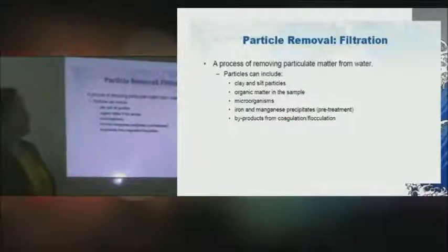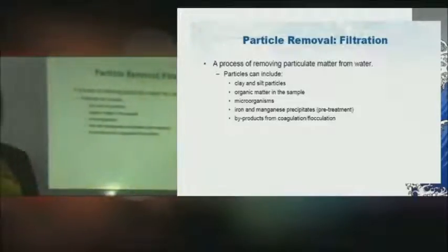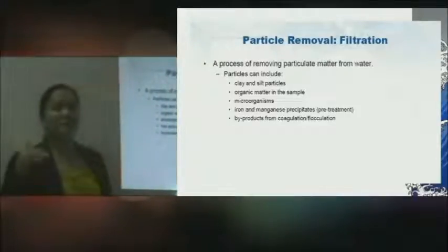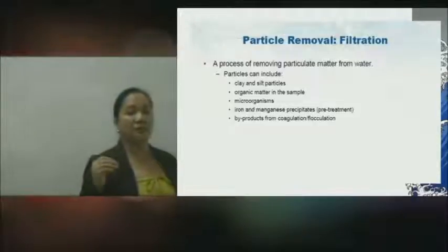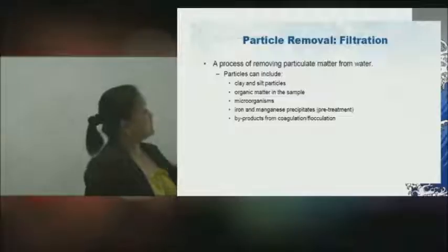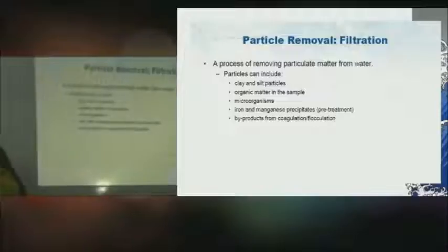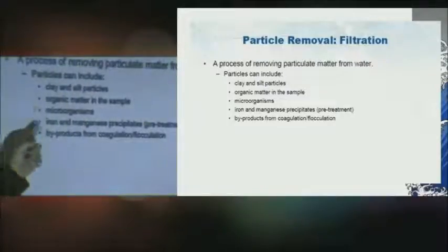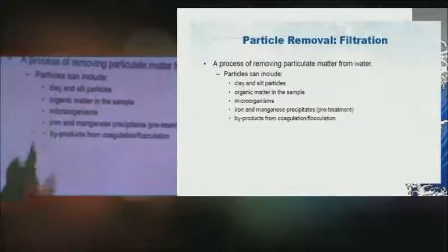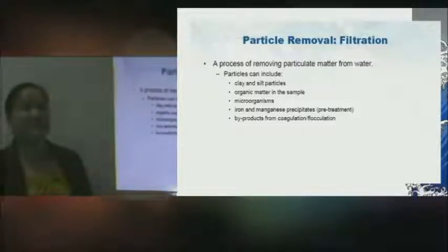After undergoing the sedimentation process, the next thing would be your filtrate or your effluent, sometimes called overflow, which will now be further filtered. Now, filtration is a process of removing particulate matter from water. Particulates would include the following. So you would know that these particles have various sizes, and therefore that would tell you what kind of filtration is to be implemented.